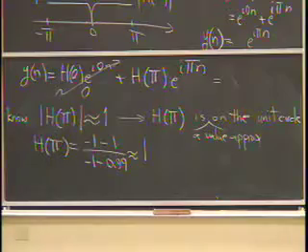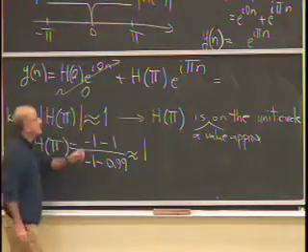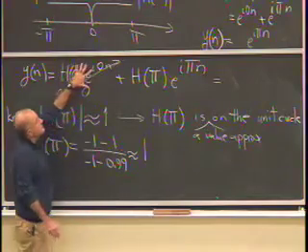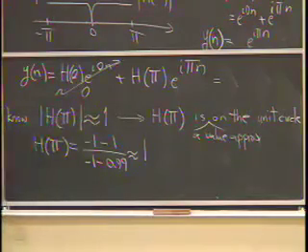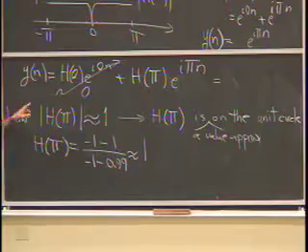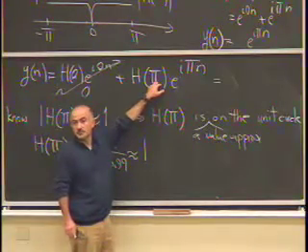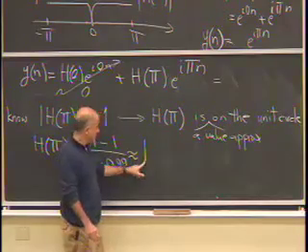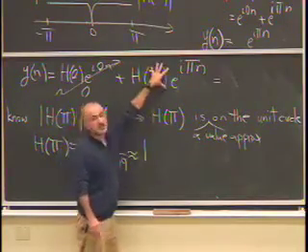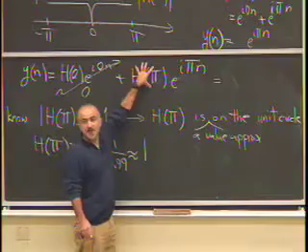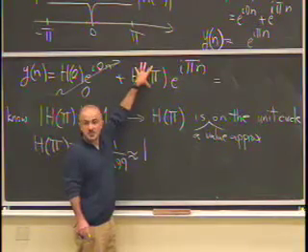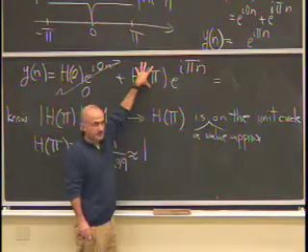This turns out to be approximately equal to the real number, positive 1. But the main point of the notch filter is that it kills this zero frequency. Okay? If I'd given you the other frequency, if this had been, say, pi over 4, you wouldn't have gotten a real number out. This would have been a complex number.